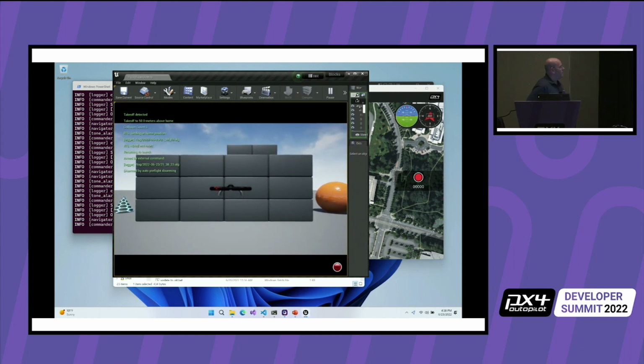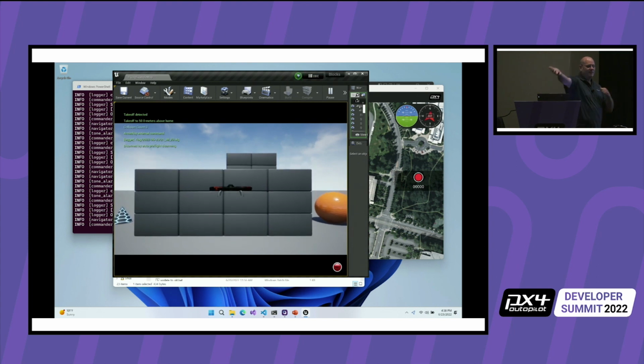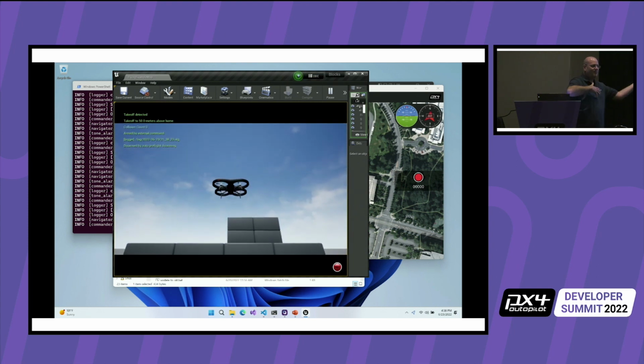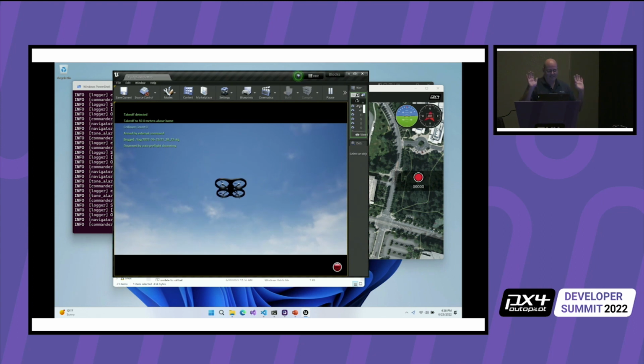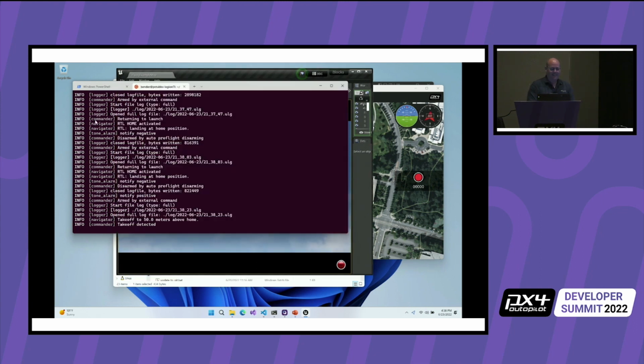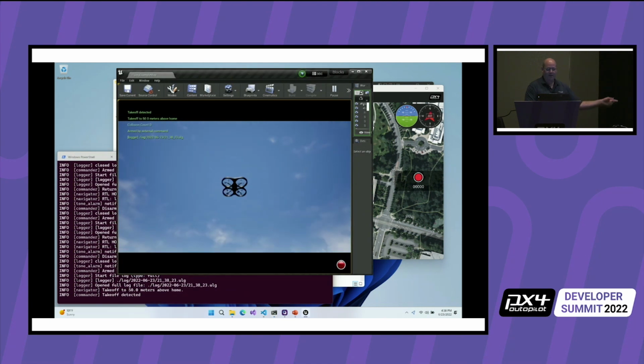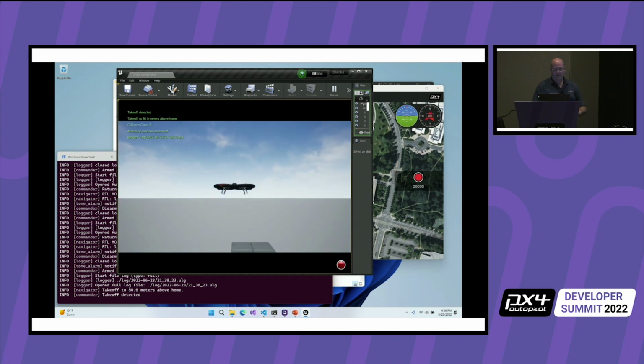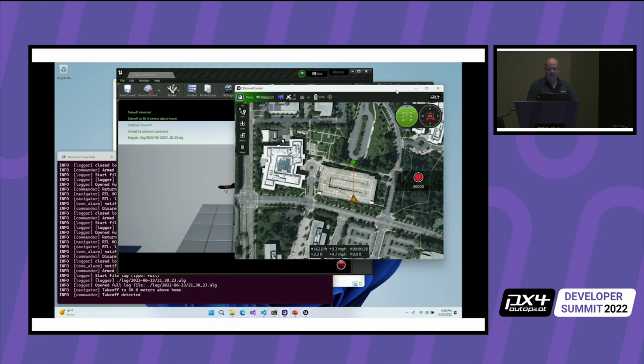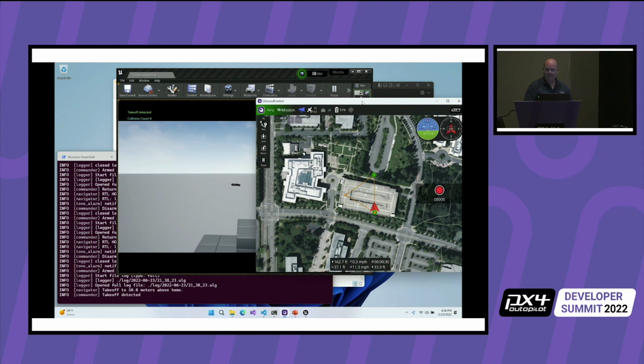So, the reason was because when I stopped QGroundControl the first time, it thought it had uploaded the mission and it wasn't. And anyway, so welcome to my world. So now you can see PX4 is running in the background. We're running AirSim here, which is the simulation. And then QGroundControl's doing its thing, flying the flight plan here all off of WSL. Ta-da. Good? Yes? Okay.